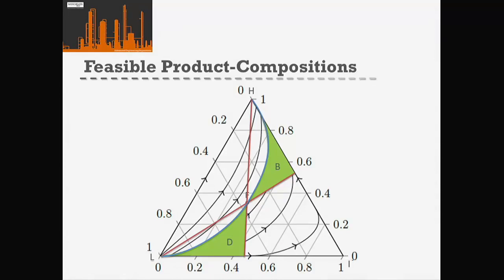Okay? So this brings us back to that essentially very first example with the azeotropic distillation, where I started to draw the different distillation options on, the direct and the indirect sequence. Okay? And we said that there's only those two options. We couldn't actually have the third option, which was separating the intermediate boiler off first by itself.